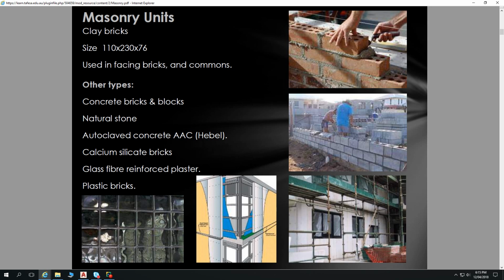So remember that. Now that's the size of the brick, and if we're going to be calculating wall heights and things like that, we always add 10 millimeters to our dimension. So for our height of 76, we'll add a 10 millimeter mortar gap. So every brick provides an increment of 86 millimeters to our height. Of course, not all mortar gaps are going to be exactly 10 millimeters, but as an approximation, that's what we arrive at, and that's what bricklayers lay their bricks to: somewhere close to 10 millimeters.